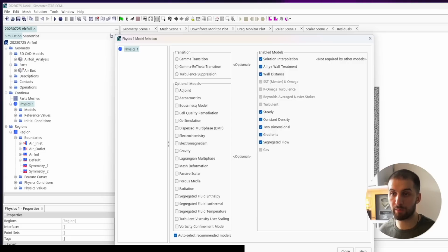Firstly, the K omega model excels in boundary layer resolution, and the K epsilon model can be less accurate in the near wall region because it makes assumptions about the behavior of turbulence in the near wall region. It's very important to accurately model the boundary layer behavior, especially for airfoil simulations, as it significantly influences lift and drag and all these parameters that we'll have a look at in the post-processing stage.